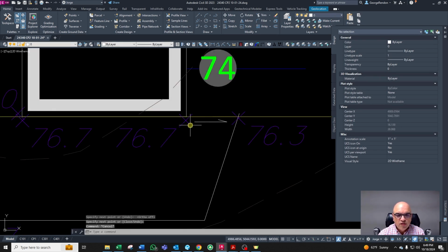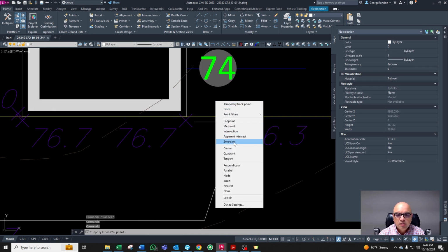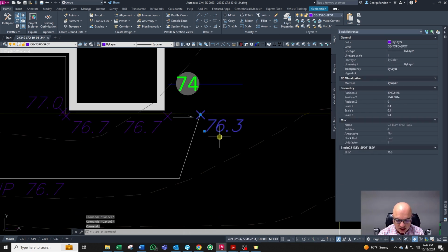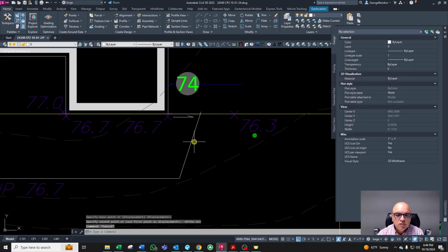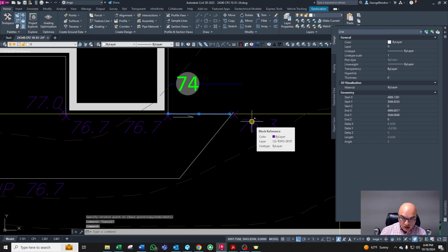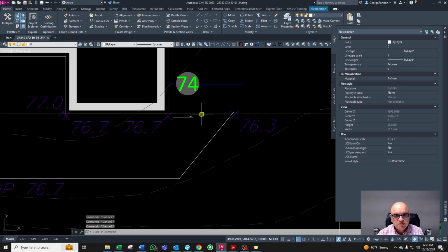So this is 0.4 in this distance, and we need to calculate this distance to see if we are okay. This distance is 4 feet, so 0.4 divided by 4 feet is 10%. This is too much. So we need to move this over and have this slope. Now we have 0.4 divided by 8.54, which is 4.6%. This is perfect.